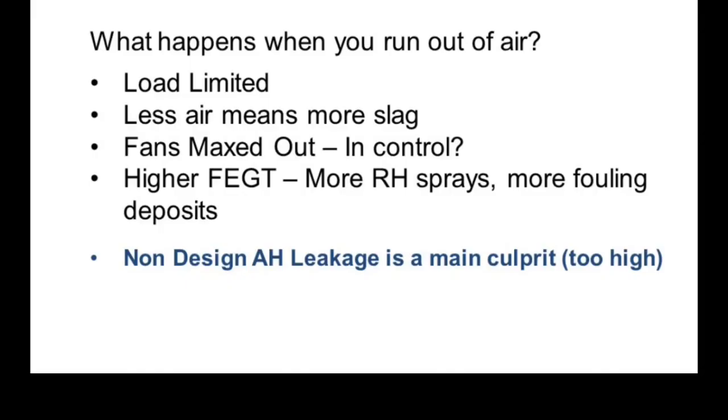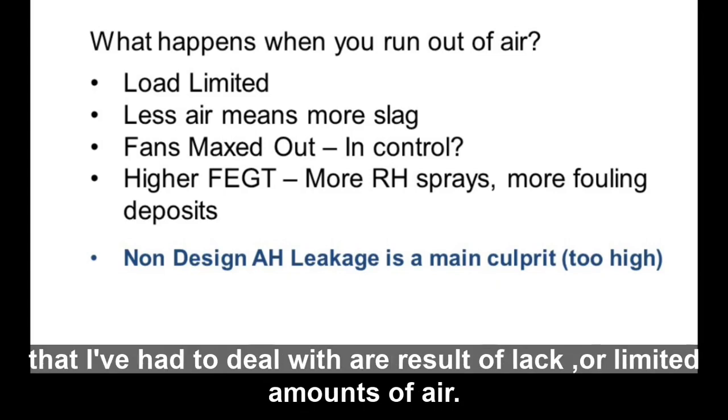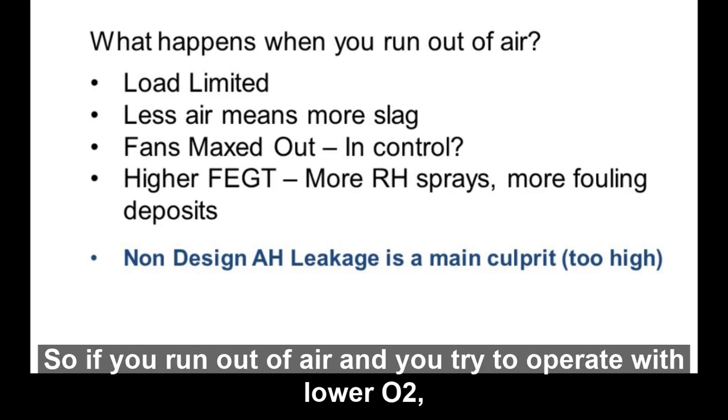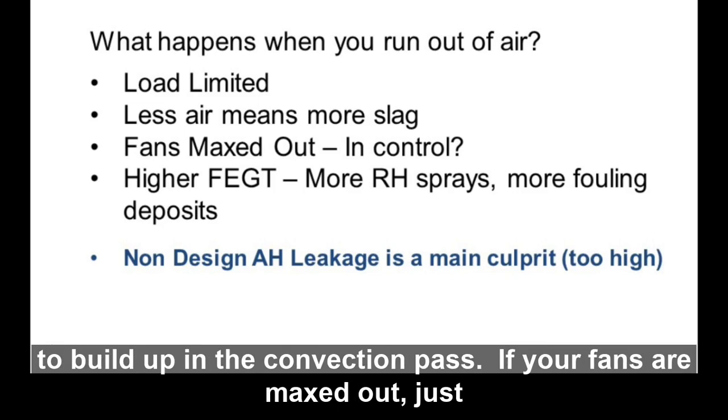A couple of important considerations is that a lot of slag experiences that I've had to deal with are a result of lack or limited amounts of air. So if you run out of air and you try to operate with lower O2s than maybe what you normally run at, you might be asking for slag to build up in the convection pass.